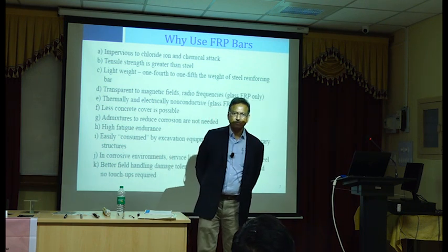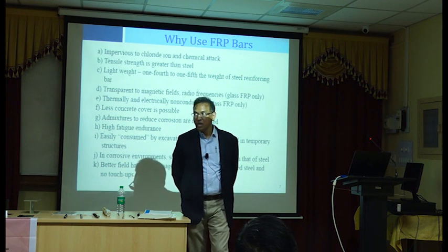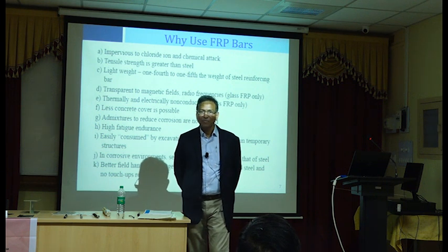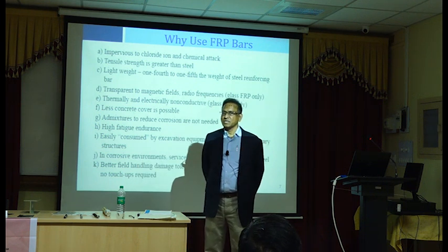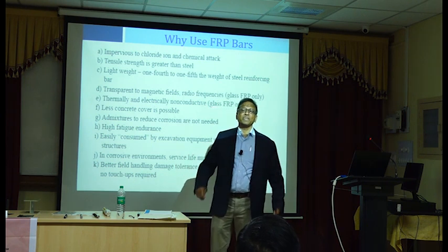Why not? You cannot transfer the tensile stress to the concrete. From the durability point of view, it's very easy for the moisture to ingress. But moisture ingress is not a problem for me because FRP is supposed to be corrosion resistant.